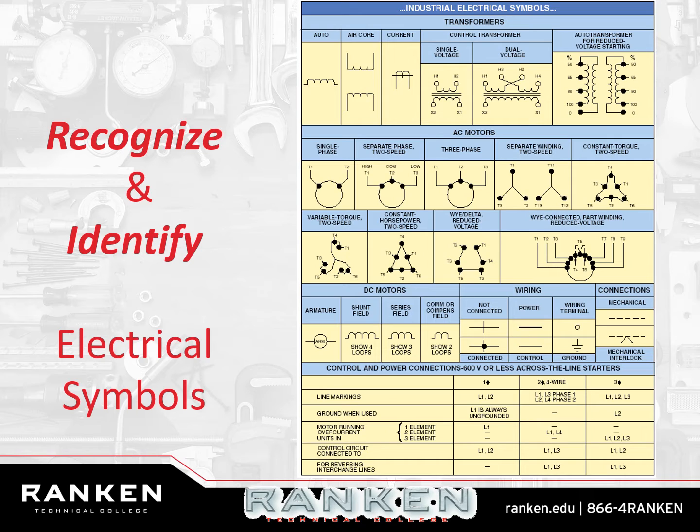Also transformers with iron cores and air cores. The big one's going to be these dual voltage transformers. You guys should have seen a dual voltage transformer by now, right? Anybody not seen a dual voltage transformer? Yes. Yeah, on the other side in Langenberg. Yeah, all of those are pretty much dual voltage transformers, right? You can wire them up for high volt or low volt. 480, 240, 240, 120. Everybody on the same page?